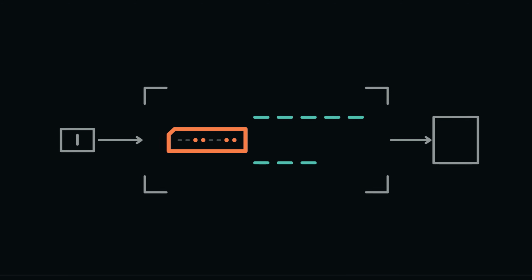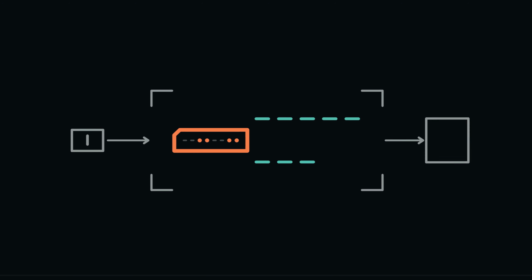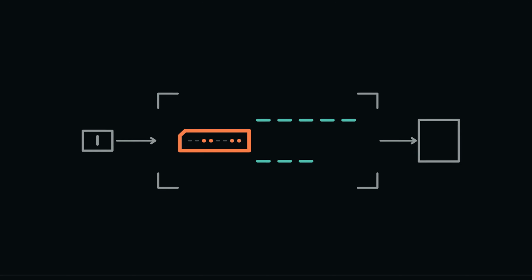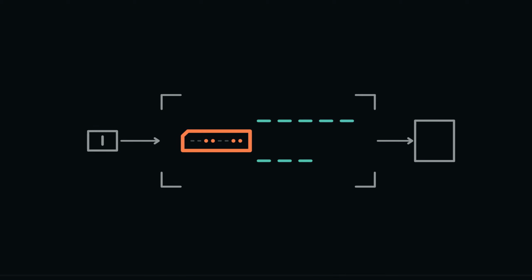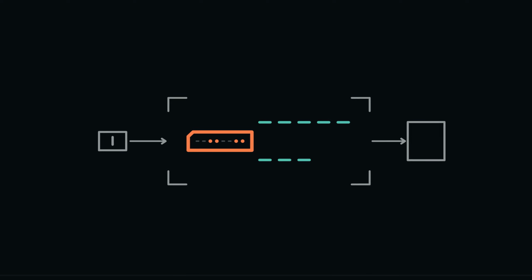A program begins here as bytes already placed in memory. The first byte of each SE8 instruction identifies an operation and, when needed, a register. The second supplies an immediate value, a direct address, or a branch target. The processor does not read the comments printed beside the program. It receives only these encoded bytes, a reset program counter, the starting register and flag state, and any external inputs scheduled to arrive. From that complete initial state, every later state must follow from the specification.